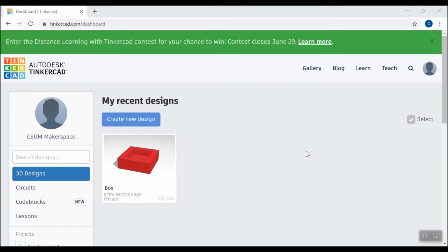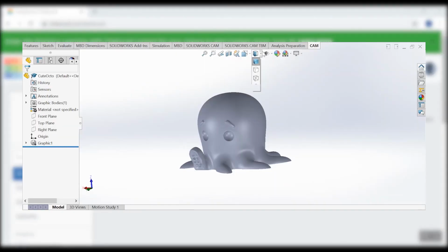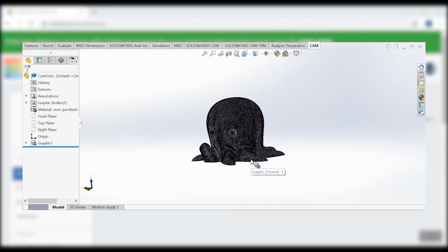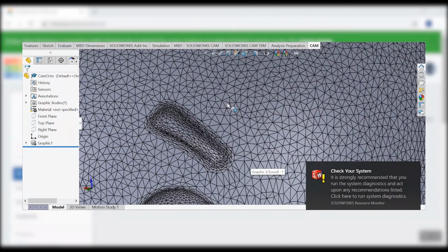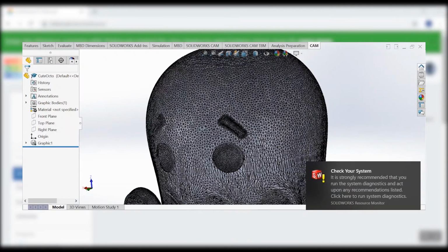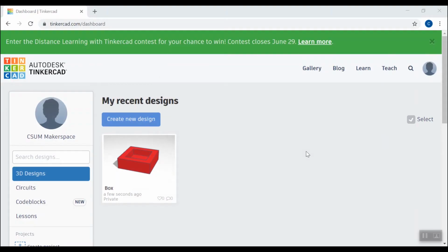TinkerCAD is also an easy way to edit existing 3D models. Normally, STL files like the ones we get from Thingiverse are difficult to edit. This is because an STL file stores the 3D object as a surface mesh of triangles, not just the shape we see. In TinkerCAD, however, we can treat STL files as regular old solids.